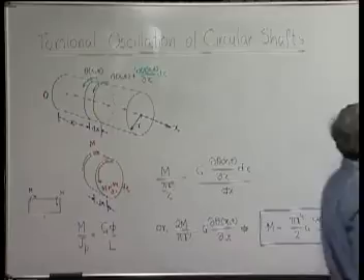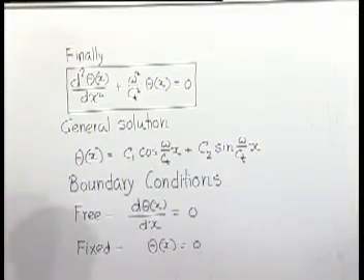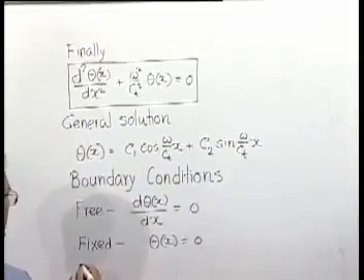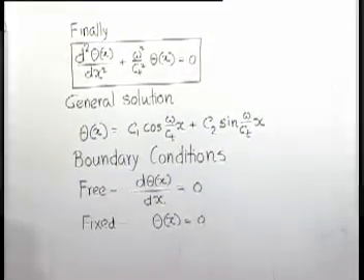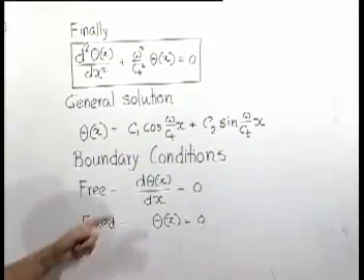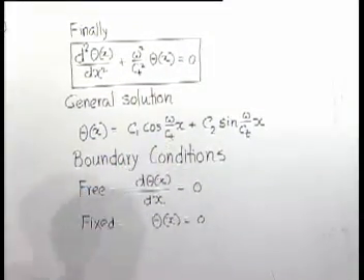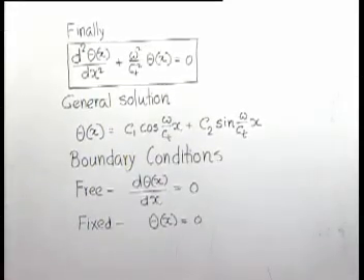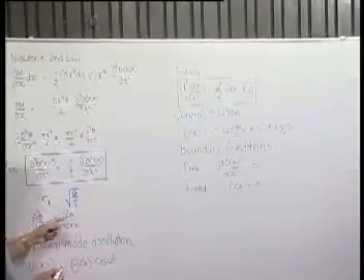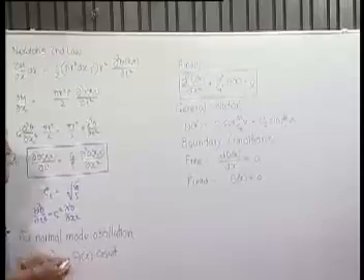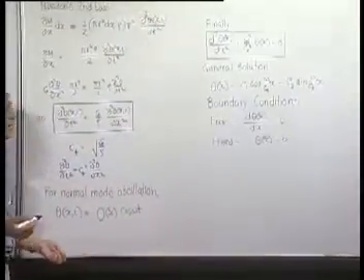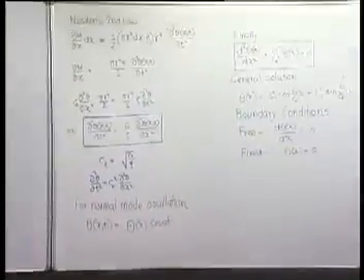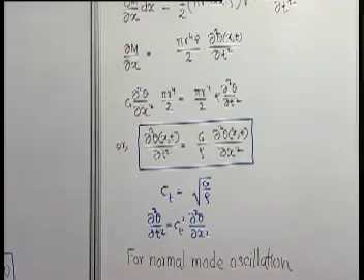So similarly, we can proceed to solve various kinds of solutions, and we will get exactly similar expressions, only here that C will be replaced by Ct, whose value is equal to square root of G by rho. In case of longitudinal wave propagation, it was square root of E by rho. So we will not repeat that. Rather, I think we would like to solve an example.